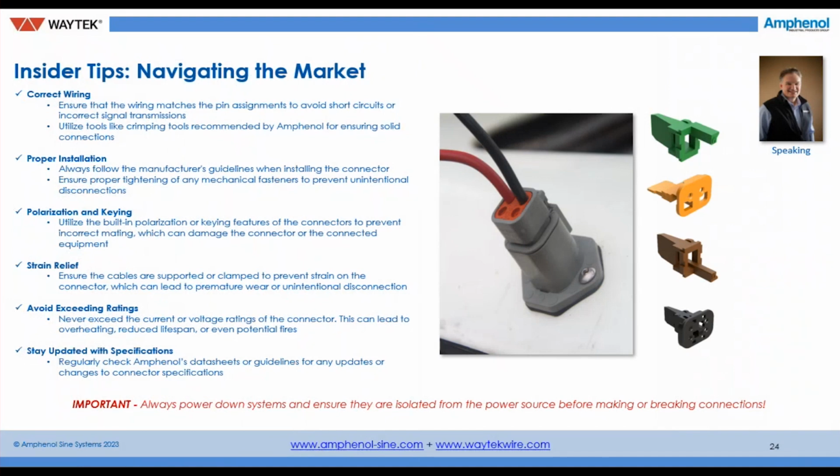Now, navigating the market, when we talk about correct wiring and proper installation, polarization and keying: utilize the built-in polarization and keying features of connectors to prevent interconnect mating. Well, we've got a great example of that over on the right-hand side. When you look at what we call wedge locks, you've got a green wedge lock, an orange, a brown, and a black. If you look very closely at the orange and the black, you can see there's 4 holes in the orange, and when you go down to the black, you can see those holes are in a little bit different place. So that involves the keying.